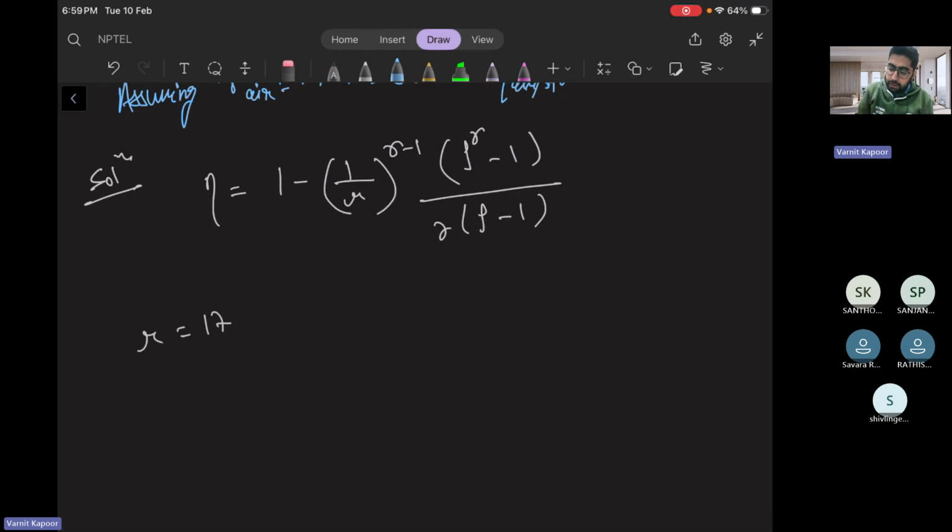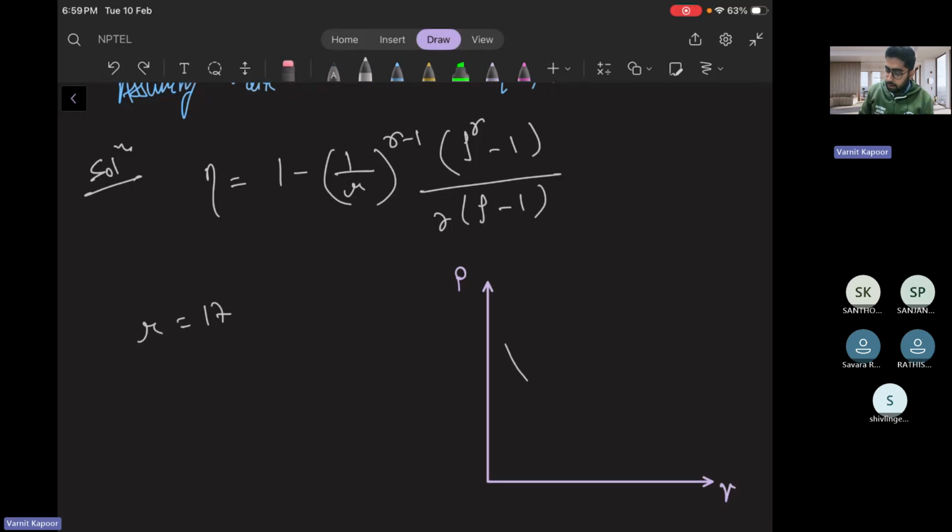When it is said like that, the cutoff. So if you go to the cycle once again, the pressure volume plot, if I make 1, 2, 3, 4. So this is your process: isentropic compression, heat addition at constant pressure, isentropic expansion, and heat rejection at constant volume. So cutoff takes place at 10% of the stroke.